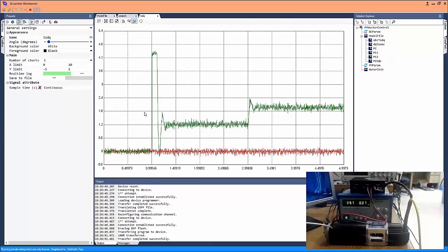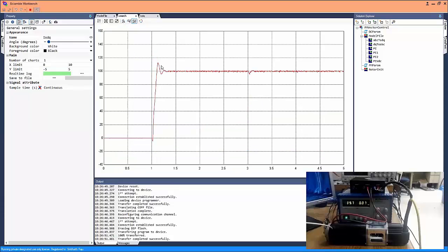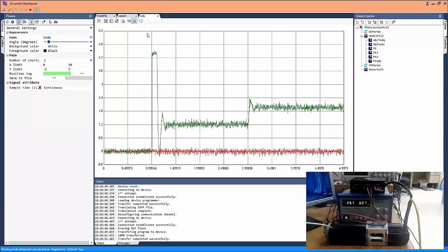There is an increase in the ISQ current when the motor is accelerating because of the reference change at time equal to 1 second, and once the motor speed reaches steady state at approximately 1.25 seconds, the ISQ current settles down to the residual current that is needed to maintain just the frictional losses. And at 3 seconds, as soon as there is a step in the load torque, the ISQ current increases to satisfy both the load torque as well as the torque due to the viscous friction.